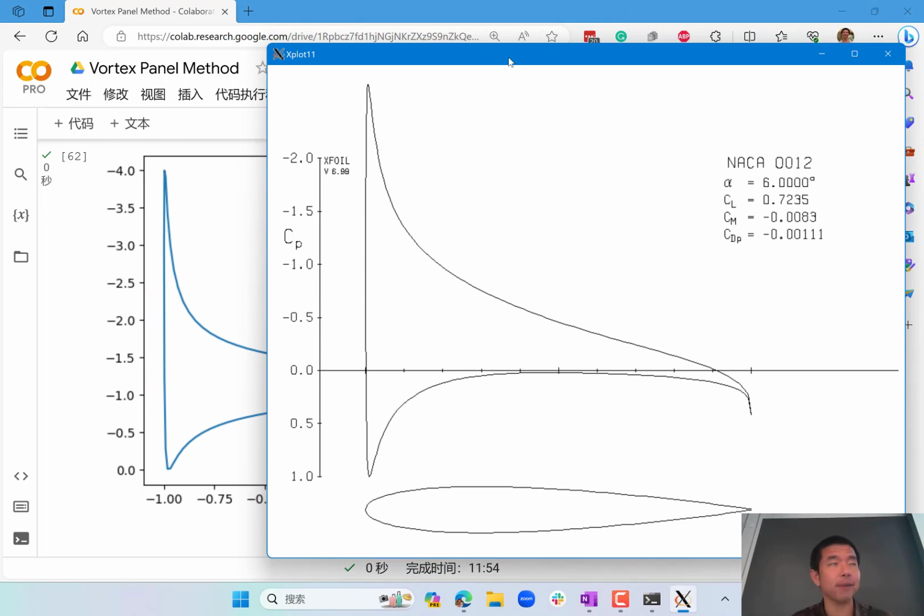Okay, so that kind of completes our lecture on the way of going from the geometry, in this case of an airfoil or an ellipse, to the distribution of vortices that we can use to compute what the flow field is like, and then from the velocity field, use Bernoulli's to compute the pressure field. And next lecture we'll go from here and look at the consequence of this pressure field, right? And how the pressure field changes as I change my angle of attack and the geometry of the airfoil itself.